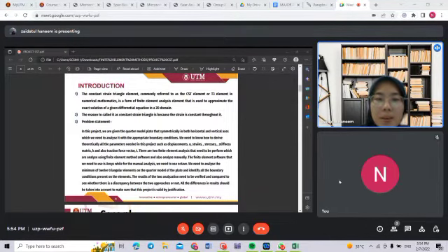One of the first elements that was frequently employed for continuum stress analysis was the triangle element with three nodes. As we learned throughout the topic of CST, we know that the constant strain triangle consists of 2 degrees of freedom per node. Nodes are numbered in counterclockwise direction and any point within the element is described by displacements u and v, where u is displacement in the x-axis direction and v is displacement in the y-axis direction. The global coordinate for the constant strain triangle element is x and y.